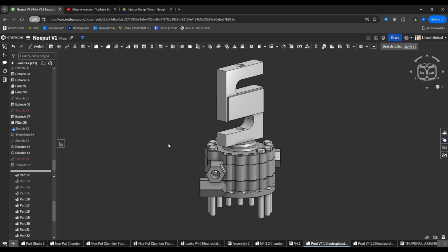So we're going to start by looking at the propellants, why we chose them and how they flow through the injector. For this engine we chose nitrous oxide and ethylene, both of which are gaseous. The nice thing about nitrous oxide is that it can be decomposed through a catalyst into high temperature nitrogen and oxygen gas. This is helpful because that temperature, around 2000 degrees Fahrenheit, is well above the auto ignition temperature of ethylene, which is only between 700 and 800 degrees Fahrenheit.